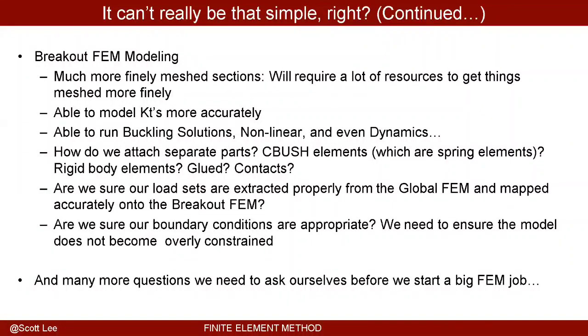If your model is overly constrained, you have these very stiff boundary forces that are going to be unconservative, because when you overly constrain your model, you're sucking out more load than you want to at your boundaries, and less load is going into your domain, into your structure. So your stress levels, your displacement levels, your load levels are going to be smaller if it's overly constrained, and that's not what you want.